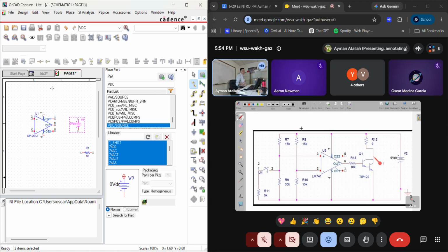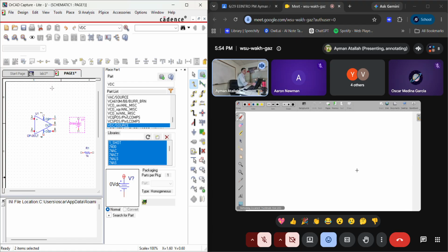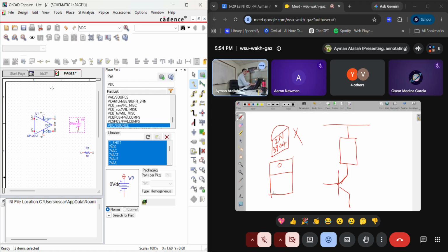The motor needs high current. What I'm going to do is connect the motor to the power supply, and connect a transistor here. The transistor itself has to be a power transistor because one ampere will pass through this. Not the transistor you used before, like the 2N3904. No, it is not a power transistor. The power transistor looks like this. It has to be connected to a heat sink. It's a big one.